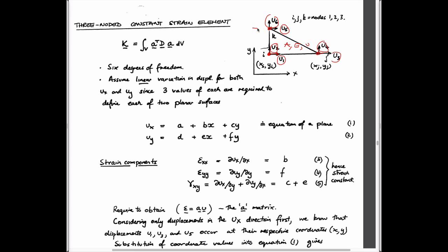And actually, as we know, we'd always have complementary magnitudes of forces at each of these points as well. So this would be F1, this would be F2, etc. We always number our element counterclockwise for the reasons that we talked about before. It's only because when you calculate the determinant which you use to get the area, you end up with a positive area. If you numbered it clockwise rather, you'd get a negative area. So it'd be easy to deal with that, but it's just convention that we do it counterclockwise.